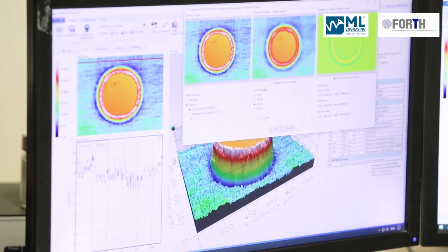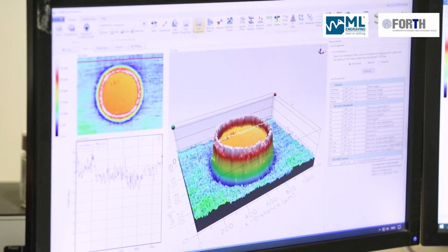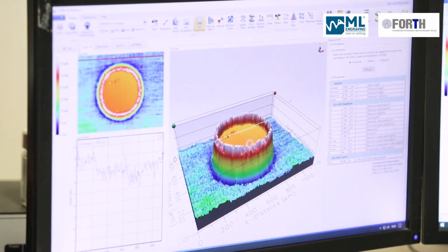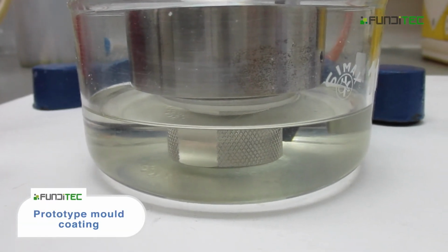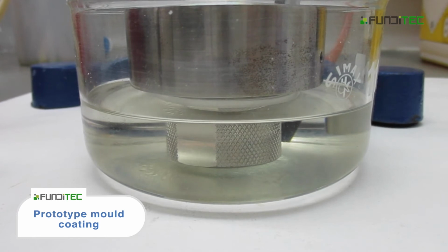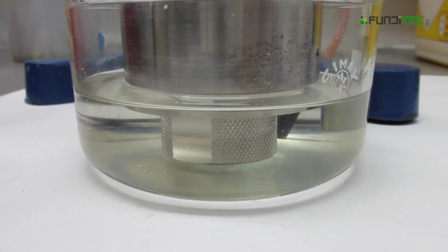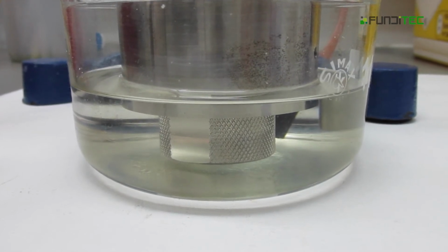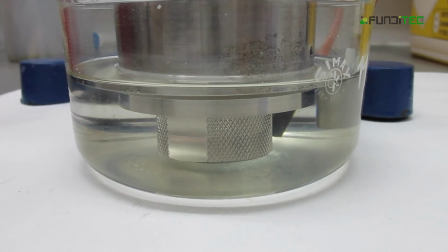As you can see, the result is stable, without recasted crowns and with the same roughness thanks to the grayscale file. In some applications, a mold coating will be necessary to release correctly the seal. This coating is applied to the prototype mold to test the mold release during the prototype phase and to make sure that the mold coating formula is appropriate for the customer use case.